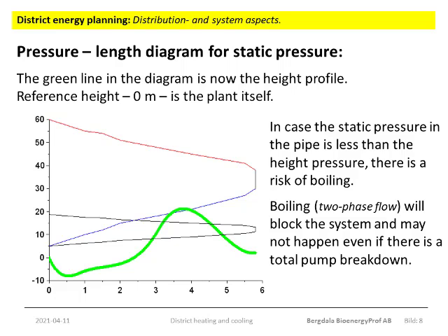To avoid steam formation in the pipes, and hence blocking, we must now guarantee that the static pressure, as calculated by the Bernoulli equation, is always higher than the pressure reduction because of the height differences. Boiling, caused because the pressure drops below the saturation steam pressure, is known as cavitation. Once the pressure again rises above the threshold, the steam bubbles formed suddenly collapse. This causes local pressure waves that may be disastrous. So cavitation must be avoided.